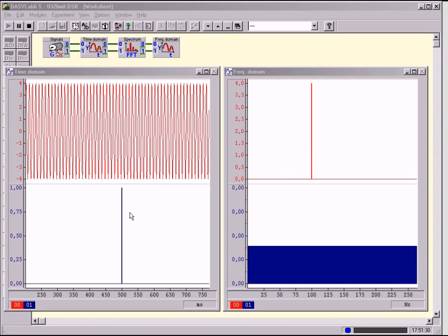A one-off delta pulse, delta t against 0, produces an infinite bandwidth, delta f against infinity. Note, a one-off delta pulse contains all the frequencies with the same amplitude. This makes a delta pulse an ideal test signal from a theoretical point of view, because, see the Fourier principle, the circuit or the system is tested at the same time with all the frequencies of the same amplitude.